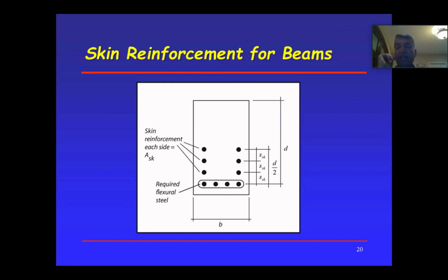The span, think about this: in a parking garage, you come in, you have a car parked on the left, a car parked on the right, and there's a driving aisle between them. The parking space on the left is 20 feet long, roughly. The other parking on the right side is 20 feet, so that's 40. You need 25 feet for two-way traffic, that's 65. You don't want any columns in there, right? You want to park and drive with no columns. So your span is 65 feet.